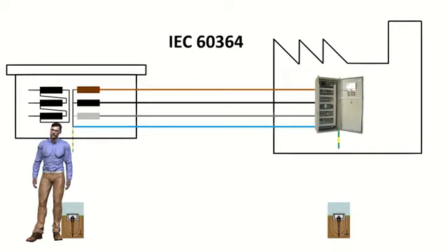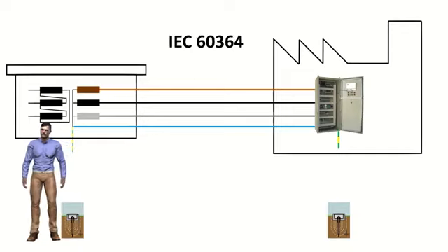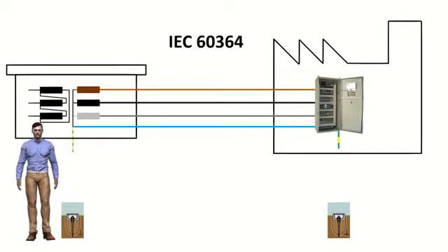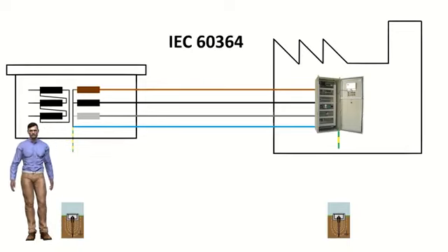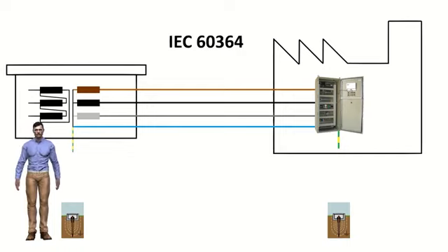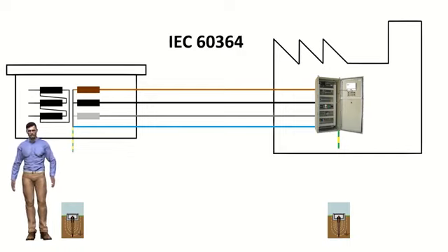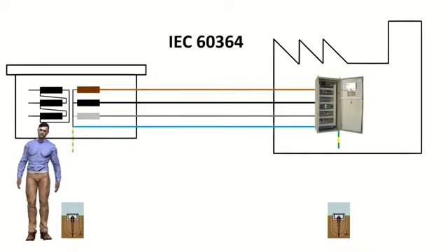However, in this electrical scheme, 2 fundamental aspects need to be mentioned that undoubtedly affect the safety of the facilities: on the one hand, the earthing of the transformation center, and on the other hand the type of grounding of the masses of the metal casings of the loads in the user's facilities. And precisely these 2 aspects will define the different electrical distribution schemes defined by the International Standard IEC 60364.